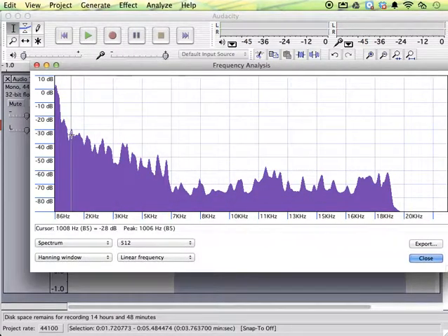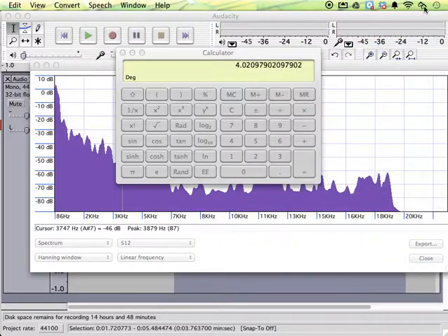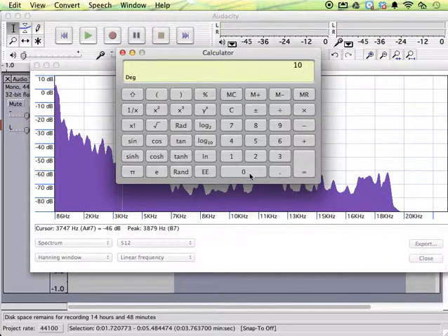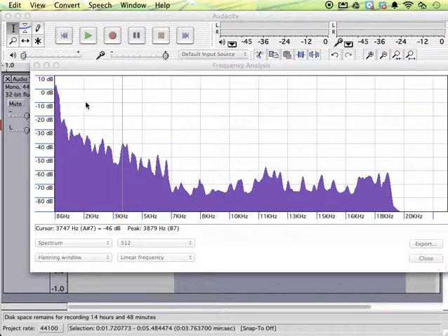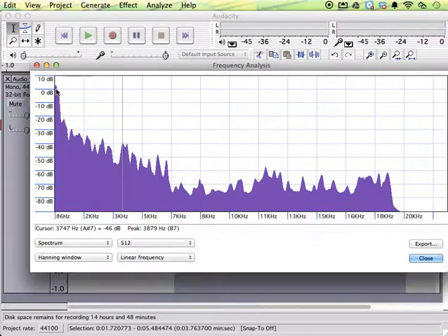And similarly, we have these other contributions. There's a 1006. So again, calculation, 1006 divided by our 143 gives about 7 times the frequency. So it seems we have a contribution of 4 times, contribution of 7 times, but these are very, very minor compared with the main frequency at 141, or we calculated 143, 144 hertz.